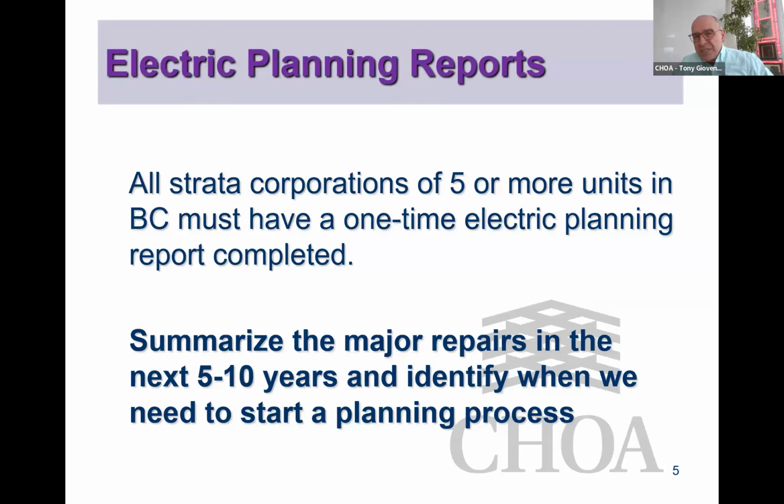Now we have jurisdictions that are changing. So if you have a makeup air system, and this is where it becomes material, in your building, and it's currently just gas for the purpose of heating in the wintertime, but doesn't do cooling, you'll find that what's coming are transitions. City of Vancouver, Metro Vancouver, the upgrades are going to have to be heat pumps to provide cooling in the summer as well. Not yet on the books everywhere, but it will be coming. So we need to start thinking about what those implications are going to be as we go ahead.